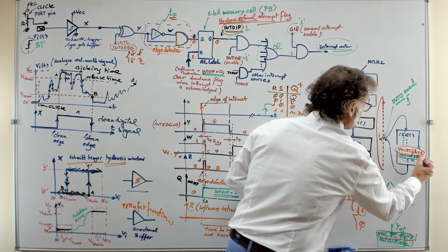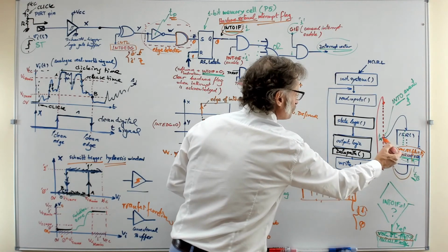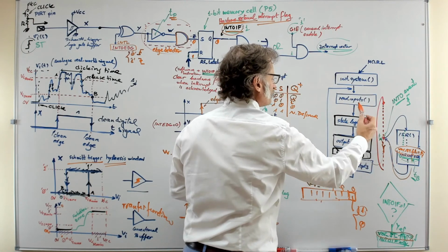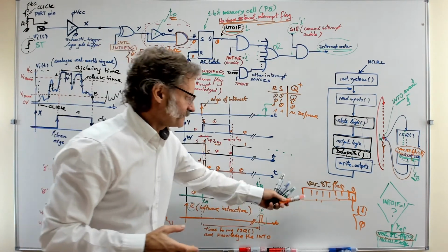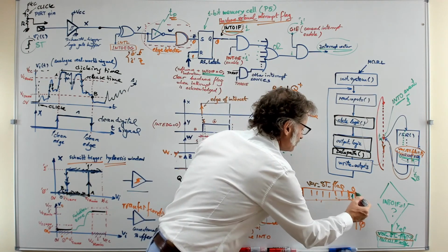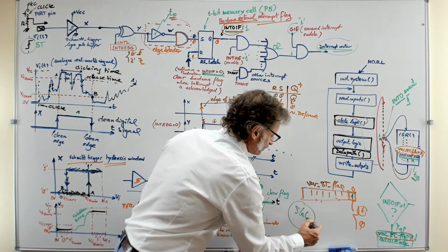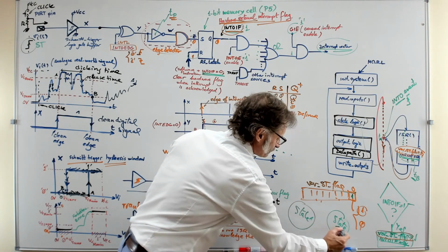If you do that, when you come back after the interrupt to the main program, and for example when you start again the loop and run the state logic, you have this flag set to 1. And this means that perhaps you can go from one state to the other state.